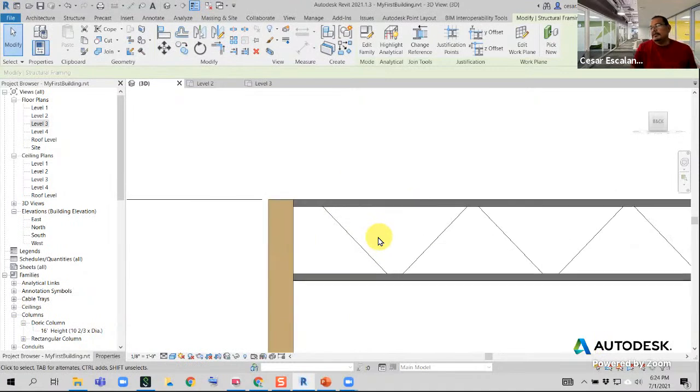So what we need to do is lower the beams, offset them a negative distance so that they are aligned to the underside of the floor. This floor is going to have, I don't know, two plywood layers, so that's about, let's say, 1 inch. Let's do an inch and a half.